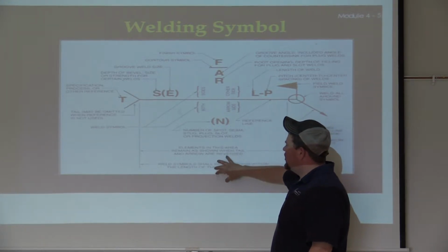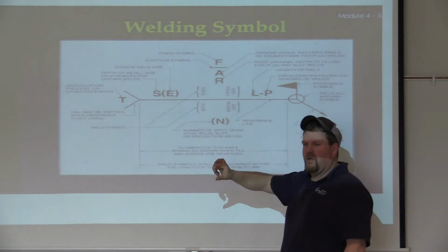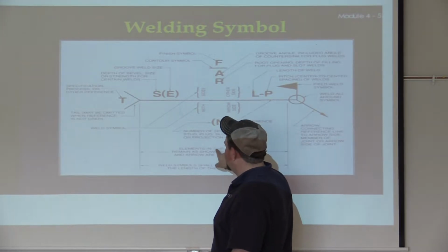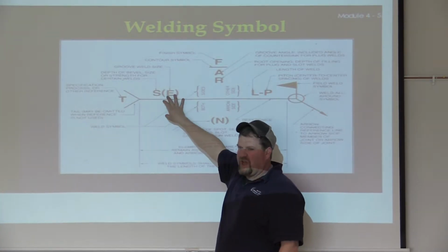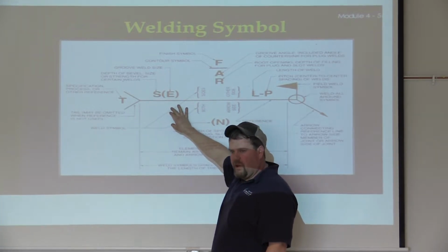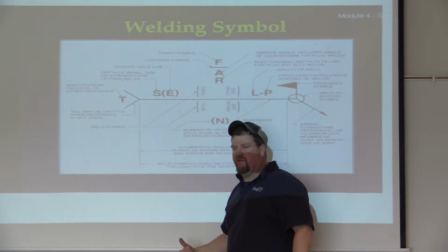We get into this also, it might tell you, like on a plug weld, remember I talked about a fillet weld, it might show you it's halfway full or half depth. Sometimes it'll tell you here, underneath this, half full instead of the size of the fillet weld. So the size would be here, maybe a ½ inch fillet weld on a plug weld. A lot of times it can tell you half or 50%.